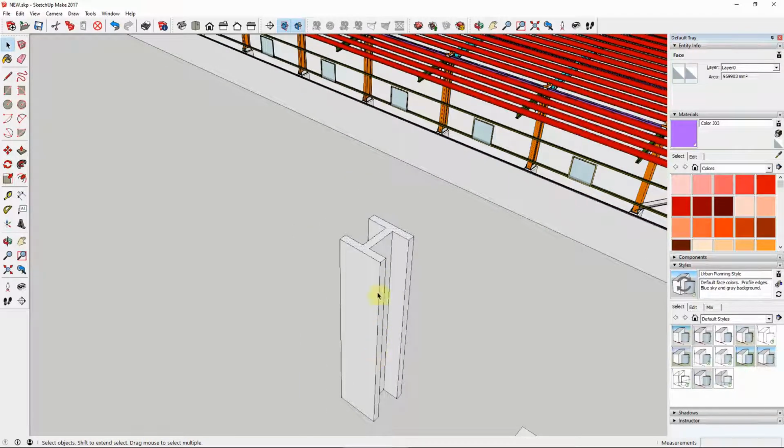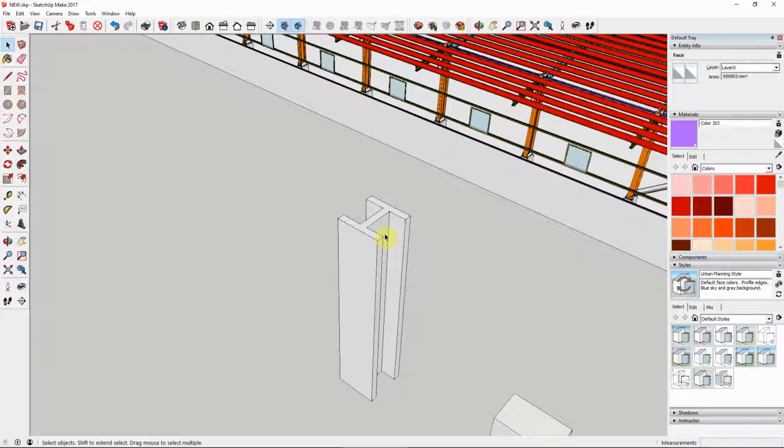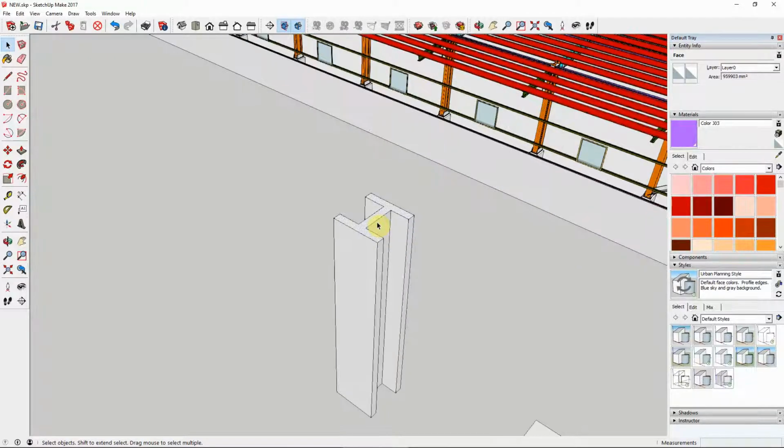In this application, if you look at this shape here, we're not looking for the load to be applied from the top flange, what we call it. I'll go back in a minute and go back through the components there. What we're looking for is the load to be applied on the entire cross section here. And that's why it's more used for columns. So it doesn't mean that we only use it for columns. It doesn't mean that anything with columns we have to use this shape. It doesn't mean that we can't use it for beams. All is possible, but what we're trying to say here is that it's more used for columns. That's why we call them universal columns.